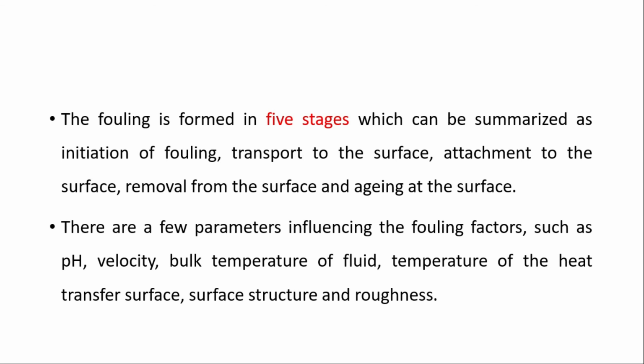Next, fouling is formed in 5 different stages, which can be summarized as the initiation of the fouling, then the fouling particles are transported to the surface, then the particles attach to the surface, then the removal from the surface, and then aging of the surface. These are the 5 different stages.